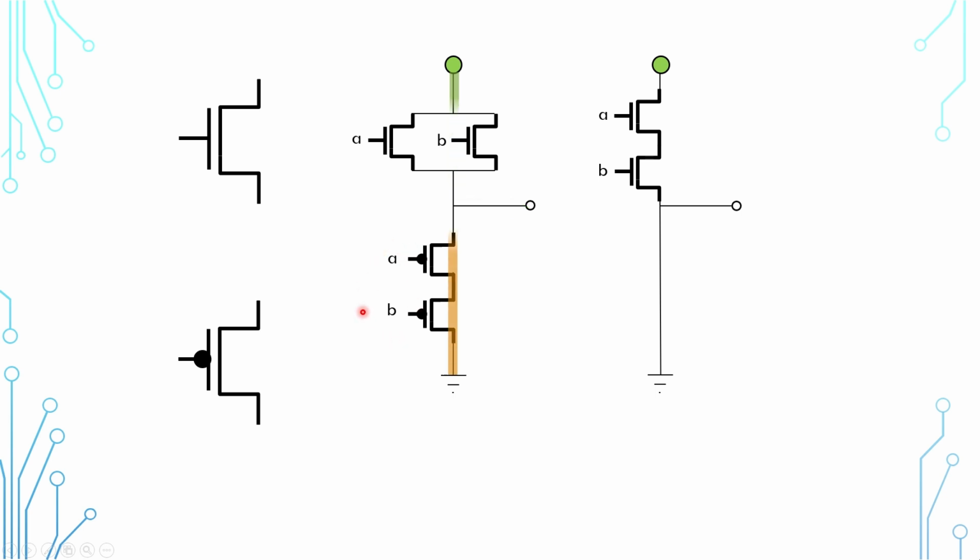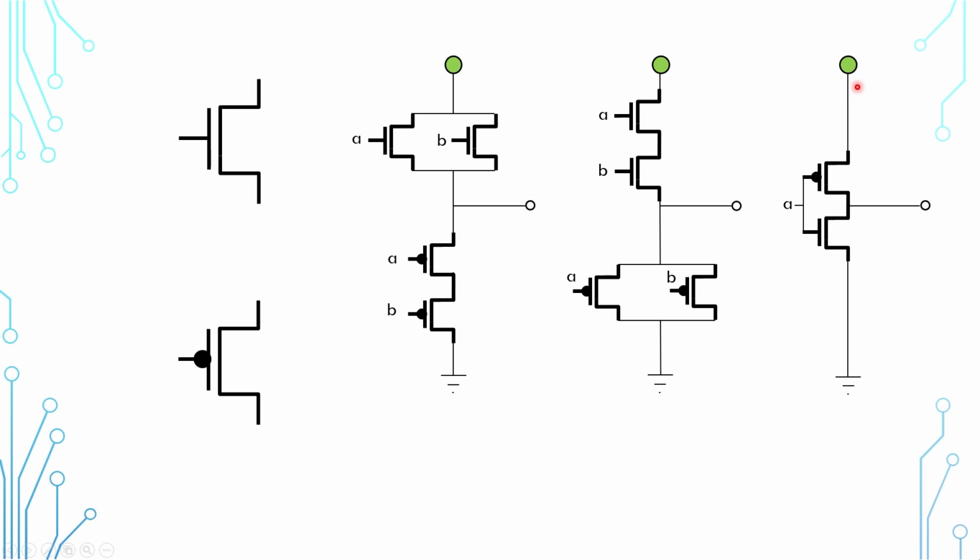When the two inputs are 0, these two transistors are enabled and the ground can drive the output. In a similar manner, for this circuitry, when both inputs are 1s, we want the high voltage to drive the output. But when any of the inputs is 0, we want the ground to drive the output. And therefore, we can create a circuitry using inverted transistors connected in parallel like this. Previously, we have looked into how this inverted transistor can invert a signal polarity. But now we know, in order to create a complete digital logic gate, we need another transistor to enable driving from the ground like this.